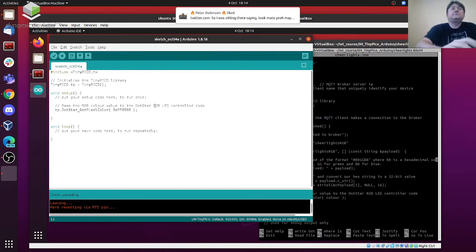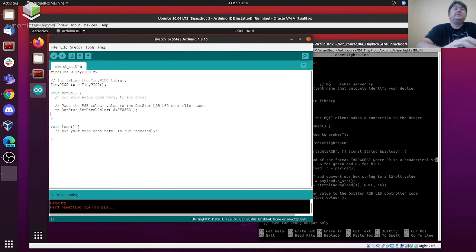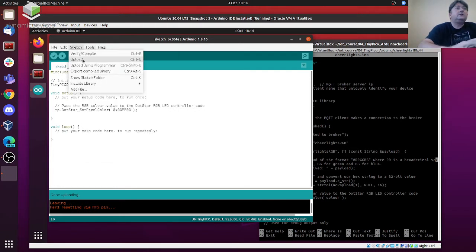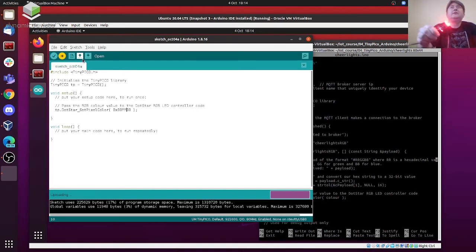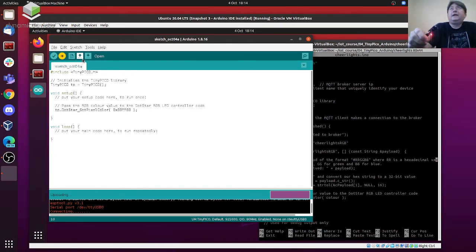So let's prove to ourselves that this is really doing what we want it to do. I'm going to change my number. We talked about RGB, didn't we? So I'm going to change this down to no red and full-on green, 255 or FF for green. And then what we'll do is we will upload it as well. It knows it needs to recompile it. It's clever enough to know that. So it's now recompiling and re-uploading to the TinyPico board.